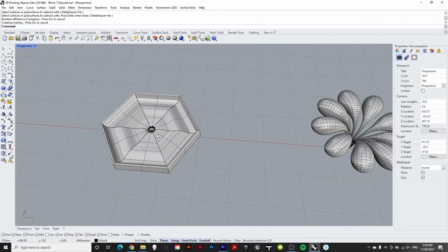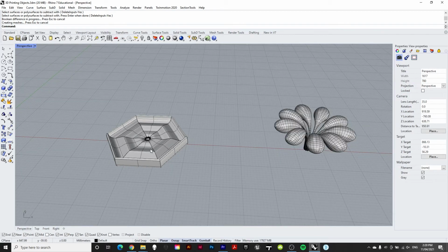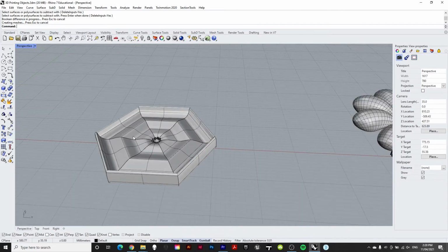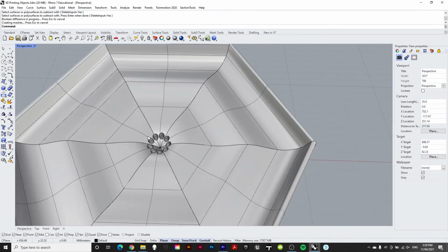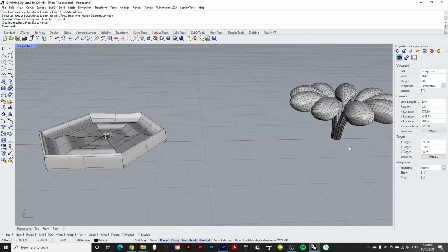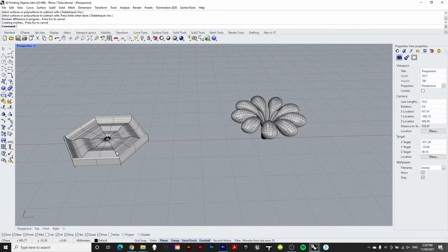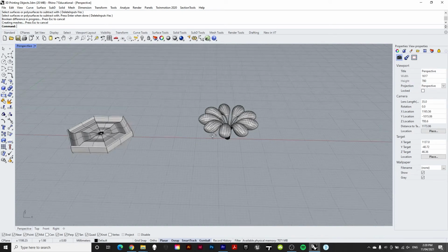So what we would do in that case is actually split this into a hybrid technology or hybrid fabrication technique. We would have this part taken to the fabricator, presumably the same fabricator, and say, well, can you please make this on the CNC? And please understand that these circles here, these holes that we have inside this base, need to have a similar tolerance to what is going on at the bottom of our tulips here. We want these tulips to slot nicely into this base with some rigidity, and they'll be able to do that for you. So we've got that separate base now ready to go with its holes already taken out.